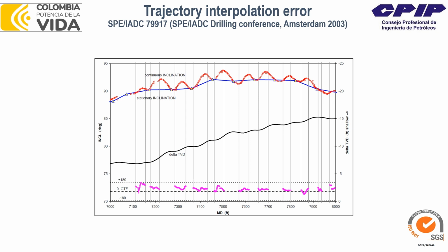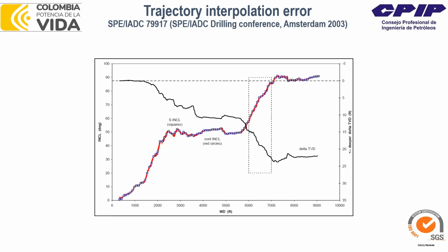And the range of this error is in meters. Okay, and if we look at the final well and the delta in true vertical depth of the actual well position compared to the calculated well position, you see it's almost 6.7 meters. For the well with almost 3 kilometers MD, 9,000 feet, not a deep well, that is a huge TVD error, 6.7 meters.